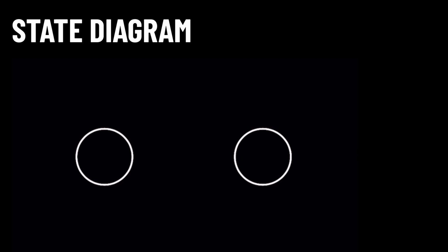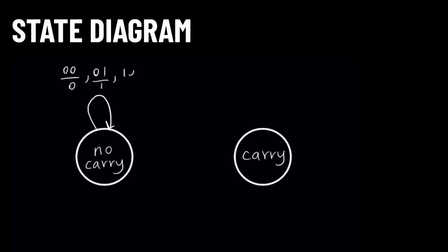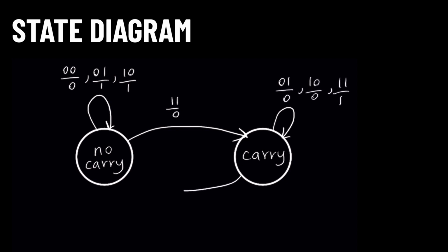The two 1-bit input values being added together will be called X and Y. The state diagram shows each of the states, as well as the transition between the states. The sum output shows the sum of the two input values as well as the current value stored in the carry, which comes from the previous addition step. The carry from the previous addition is equal to the state assignment. In this manner, you could consider the carry value to be a synchronous or Moore machine type of output.